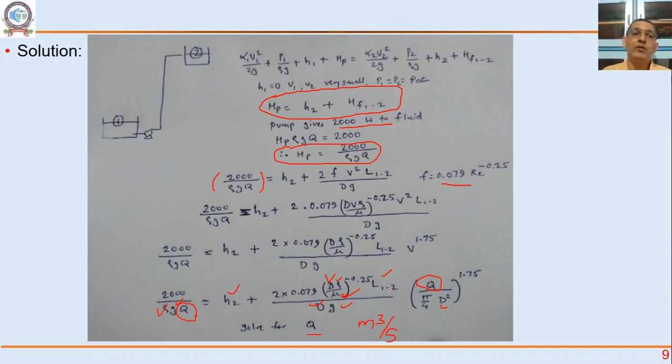So I am giving you now how much power. So again, go back to our first lecture. Head or flow rate, geometry and power required. Now what we were doing so far, I told you the flow rate, I told you the geometry, and I asked you to calculate the pump power required. Now I am giving you the power, energy, I am giving you the geometry, pipe sizes, and I am asking you to calculate what flow rate will go through. So you remember that triangle, flow, geometry and power, or flow, geometry and energy. Any two out of the three I know, the third one we can calculate.